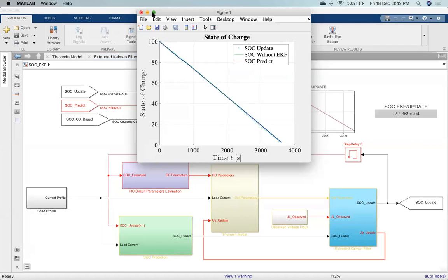So here, what I'm doing is I'm discharging the cell at 1C rate, which means if you discharge at 1C rate, it has to take 1 hour, and the SOC has to come from 100% to 0%. So that's my validation. I can go with dynamic profiles and validate my model, but the thing is, if it is dynamic and the current is continuously changing, then we can't validate ourselves whether the model is working well or not. So for that, I went for a constant current discharge test.